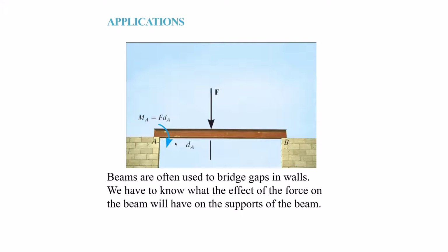So what ends up happening in this case is that we have an equation that we created from the forces, and we'll look at more examples if you got the general idea right now. We have an equation due to the forces, and we also have another equation due to the moments. We could do a moment equation about A, or we could do it about B if we wanted to. But basically, we have two equations and two unknowns, the reactive force pushing up here and the reactive force over here. So with that, we can solve for the reactive force pushing up at this point and at that point. And that's what we're going to be looking at for the two-dimensional problems.